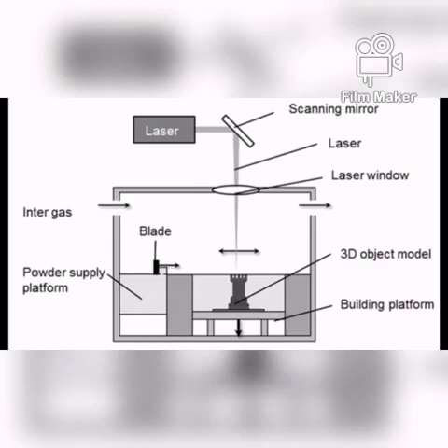put metal powder into the supply platform. After that, the device sets the scanning speed, the laser scanning interval, and the angle. After that, nitrogen gas or argon gas will be introduced into the device. After the appropriate volume of gas is loaded, an amount of metal powder suitable for one layer is deposited onto the base plate using a blade.